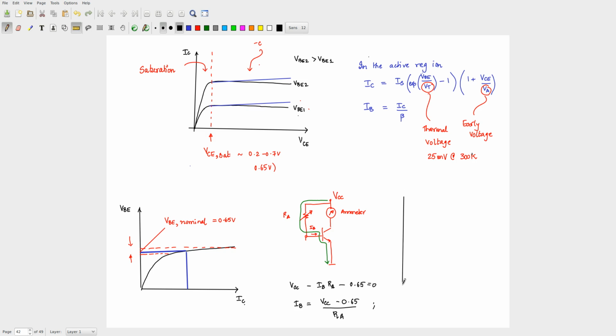So, most bipolar junction transistor characteristics, if you see in your data sheet and so forth, you will not see VBE there, right. You will see a characteristic like that, similar to what we have drawn, but they will say this is IB1, this is IB2, this axis is VCE, and this is IC. Okay. So, the characteristic is the same, it is just that you will use base current to label the curves. So, typically you may see something like this is 10 microamps, then 20 microamps, and so forth, right. At least this will make sense rather than having VBE equal to 0.65, 0.66, 0.662, things like that.